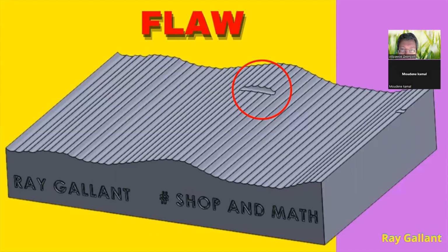Flaw is an irregularity that occurs in a surface due to cracks, blowholes, ridges, scratches. Basically anything that's not in the machining pattern. There are no finish symbols for flaws. A special note should be included on the drawing where no flaws are permitted.